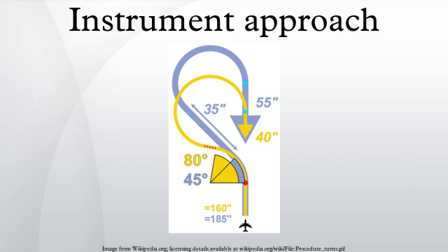The above simplified formulas are based on a trigonometric calculation. Rate of descent equals ground speed × 101.27 × tan θ, where θ is the descent or glide slope angle from the horizontal, and 101.27 is the conversion factor from knots to feet per minute. Example: ground speed equals 250 knots, θ equals 4.5 degrees. 250 knots × 101.27 fpm/kt × tan 4.5 degrees equals 1993 fpm.